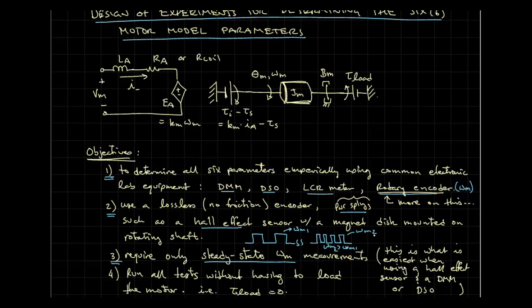Then you'll have to zoom in down to the level where you can distinguish one period from another, let the DSO measure the period or the frequency, and then pan through that entire capture.